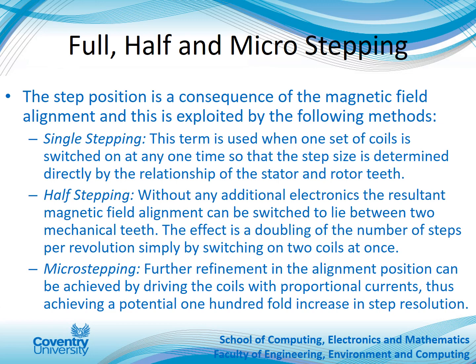If it was half stepping, you start at 12, but instead of going to 3, you go to 1:30, then 3 o'clock, 4:30, 6 o'clock, 7:30, 9 o'clock, 10:30, 12, and then you've completed one complete cycle. So you double the number of steps that you need per revolution, and it gives you a more accurate way of driving motors.